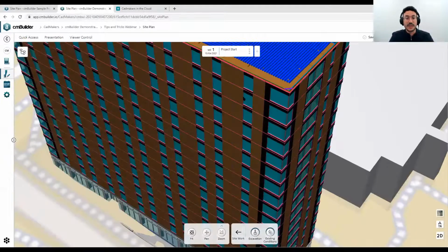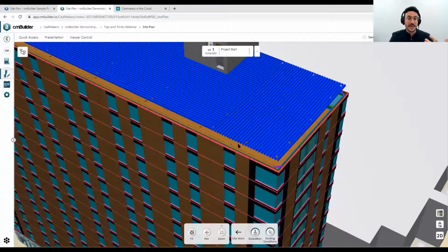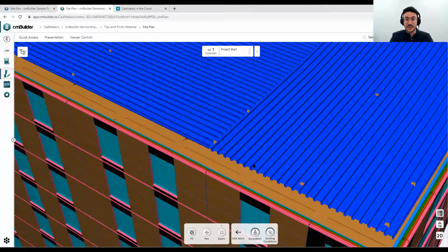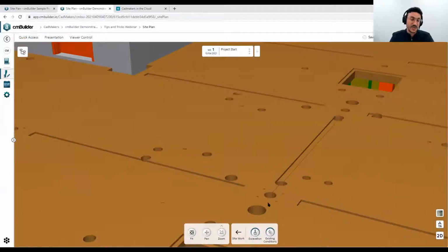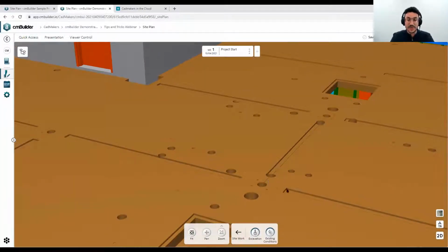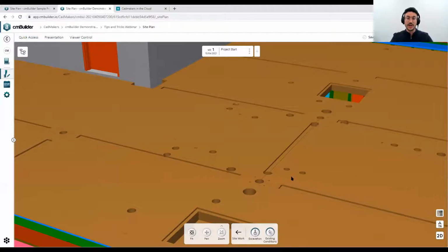So I would find out one specific element in this model that I can use as my reference. So for example, these penetrations, and I can use that penetration to bring in the model and locate it accordingly, right? So it's not always easy to find these references, but you can use faces, you can use specific snapping points, and so on and so forth, okay?